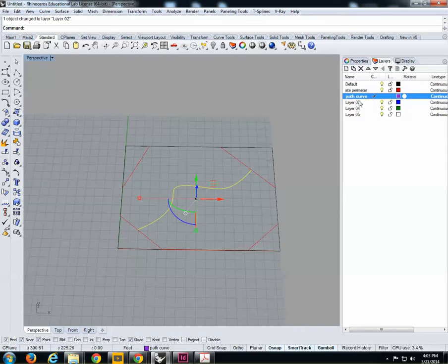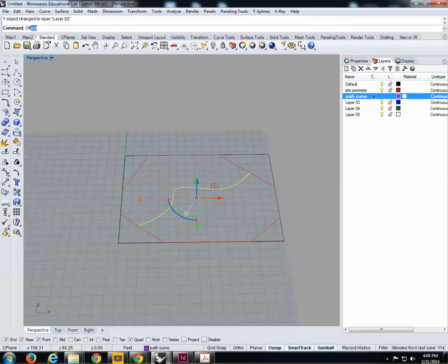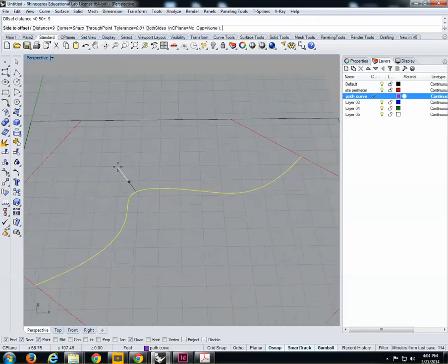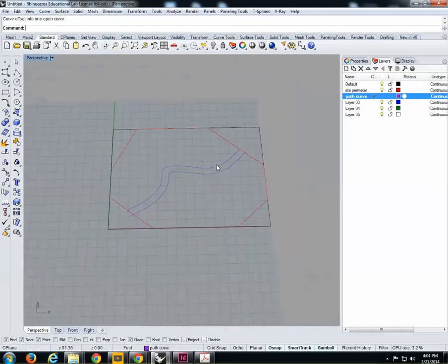While I am inside this layer, I will even offset the curve 9 feet. So I create a width for my path. Now, when you are in the offset command, I guess you have used it already, you can go under the distance and change the distance to whatever your dimension wants to be. And also you can select the side. So if I snap, I click enter now to this side, this is where my path will be generated. I went to the opposite.